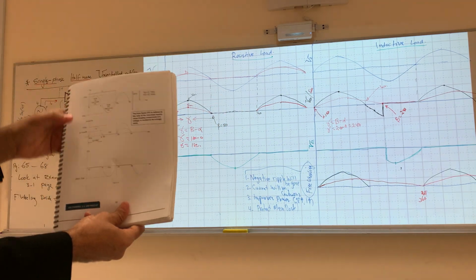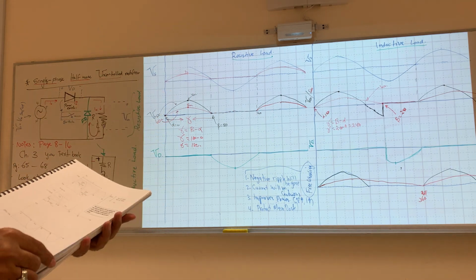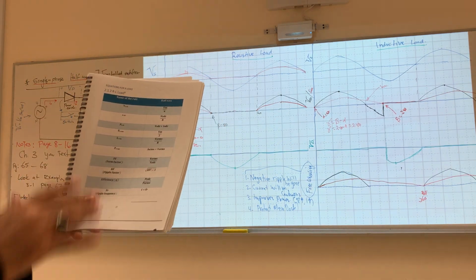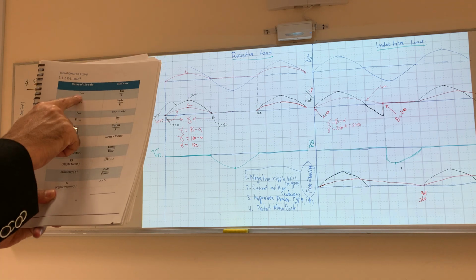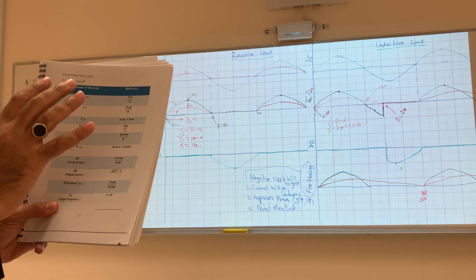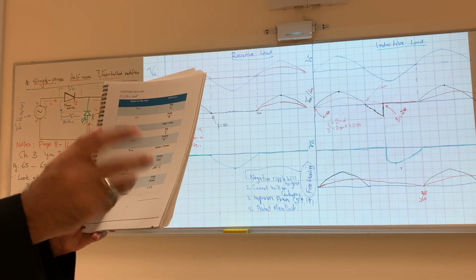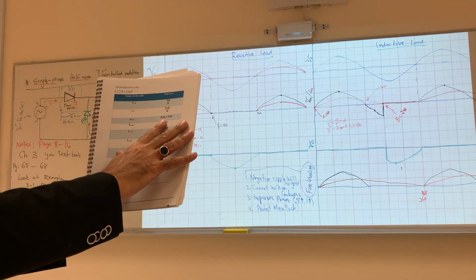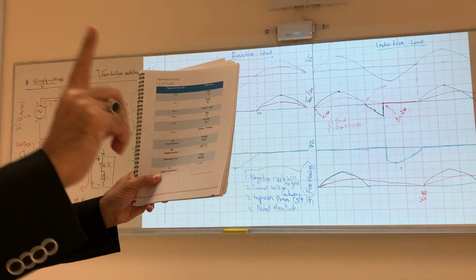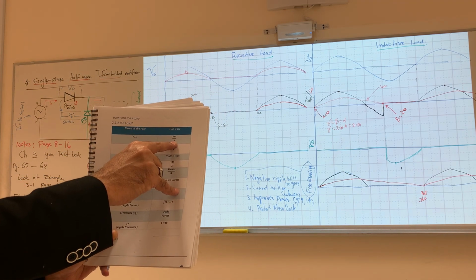That's the V source, and this is the V out and I out with resistive load. Okay, and those equations. Make sure you understand those equations. And if you have any question, you can ask me. This is the V out DC. You will find it also in your textbook, but this is a good chart for equations, and the equations will be repeated and there will be one different thing. So those equations are for both resistive and inductive, half wave. There will be one thing that will change. You see here, this is V out equals V max over pi, that's for resistive load.